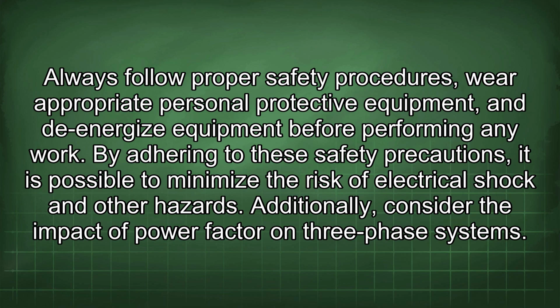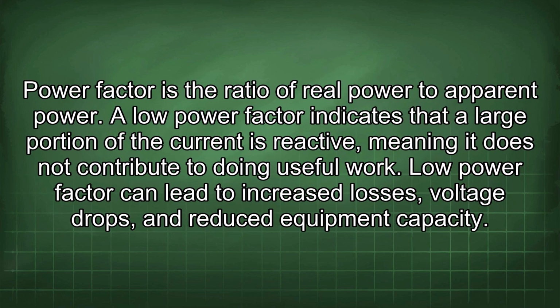Additionally, consider the impact of power factor on three-phase systems. Power factor is the ratio of real power to apparent power. A low power factor indicates that a large portion of the current is reactive, meaning it does not contribute to doing useful work. Low power factor can lead to increased losses, voltage drops, and reduced equipment capacity.